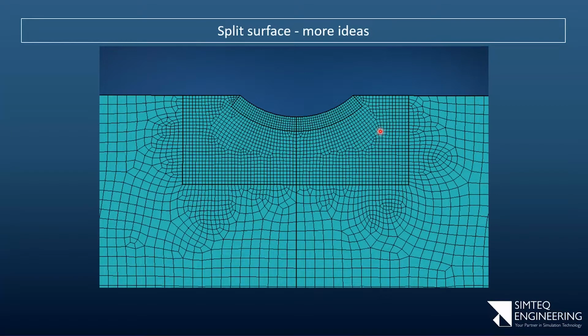Okay, so the other thing that I did here in this example was these are again 0.5 millimeter elements and these are slightly larger. So I already transitioned to slightly larger, but about let's say 0.7 millimeters, meaning I have fewer elements than I would have had, but I still have a pretty decent mesh there. But from there on, I can transition to significantly larger elements.